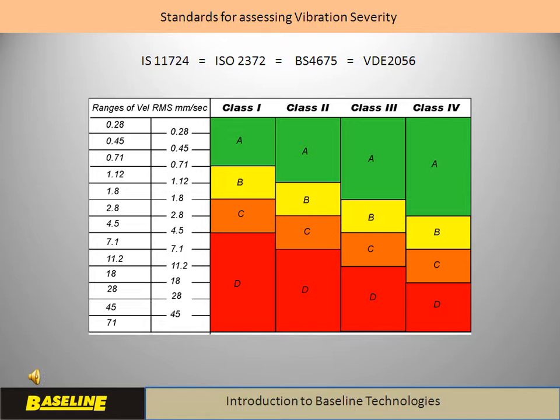It is essential to periodically track the vibration severity as measured by velocity in millimeters per second true RMS at specified points on the machine. This provides valuable insights into whether a quality level B is good or C is acceptable for a given machine. It is our experience that uncontrolled levels of vibration in the Indian context normally hover around C to D levels, and it takes conscious efforts to get these to stay within B levels.